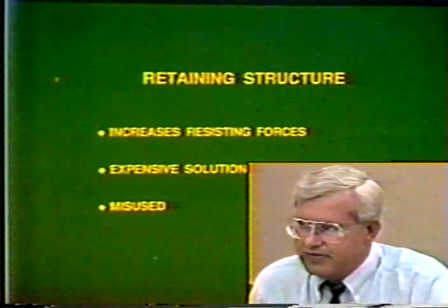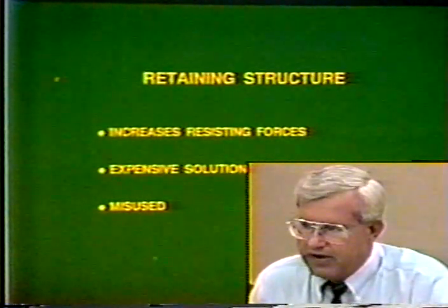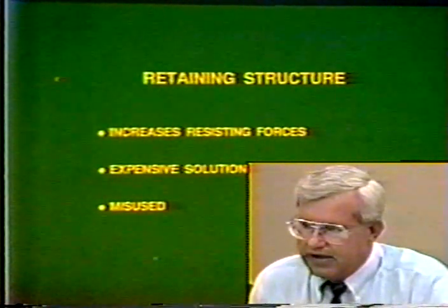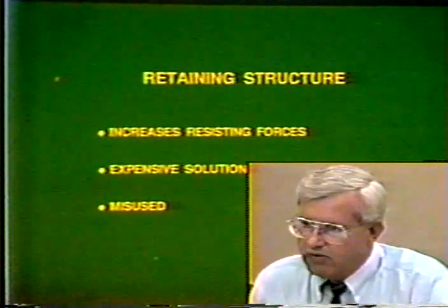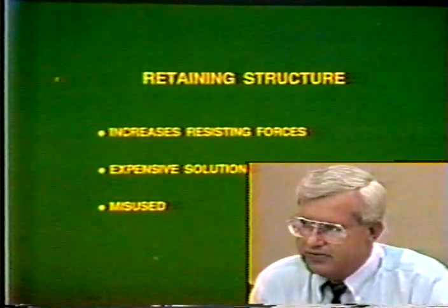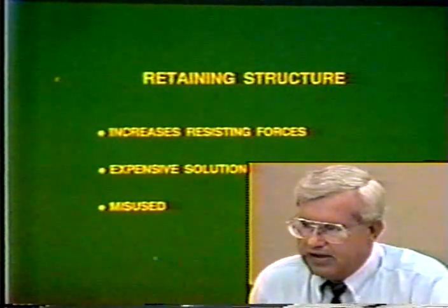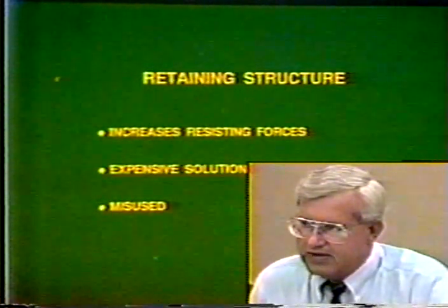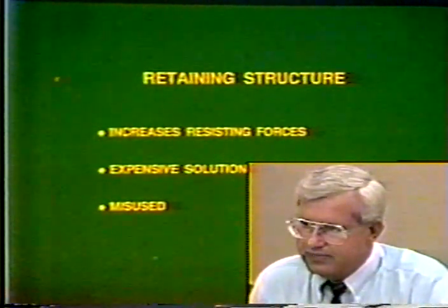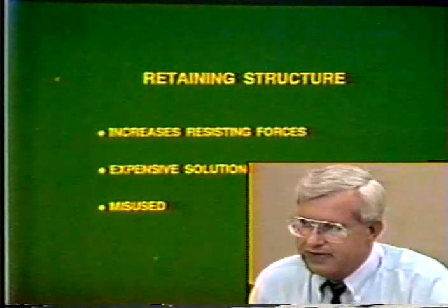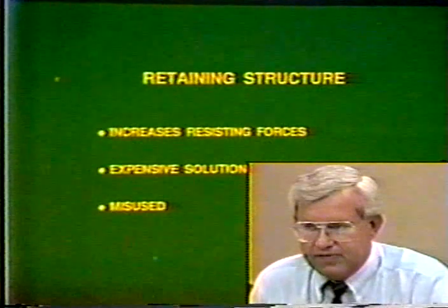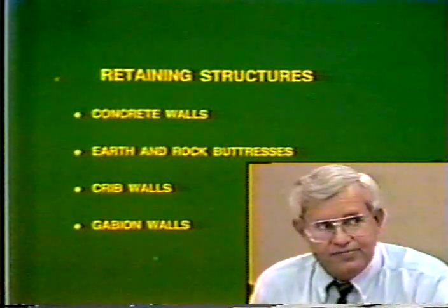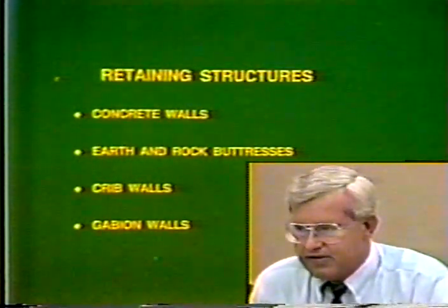Retaining structures are used quite often in highway repairs. What we're basically doing is putting a mass of material or a wall at the toe, perhaps, of the slide. But let me emphasize, this is a very expensive solution, and you should look at the other methods first before you consider a retaining structure. Oftentimes, it's misused, and we'll talk about that just in a minute.